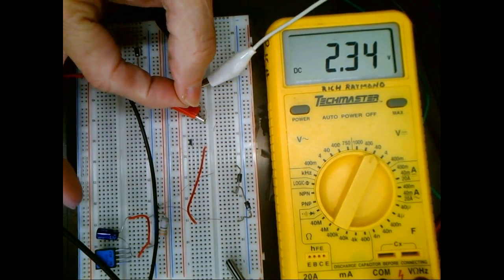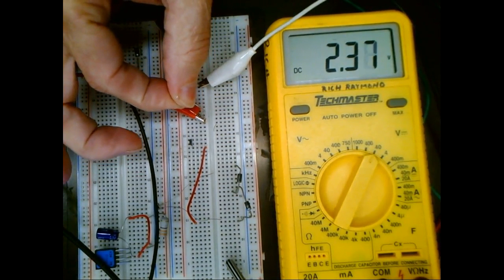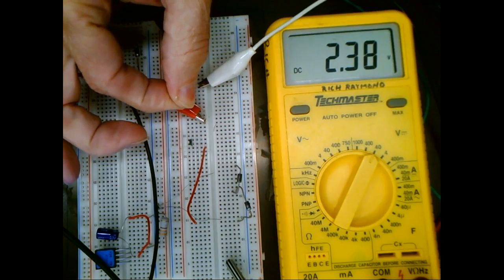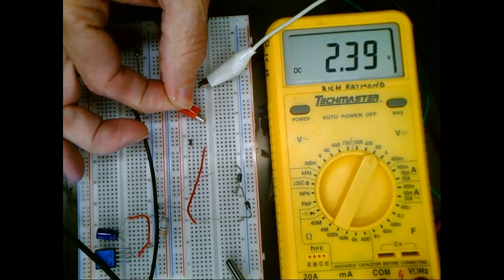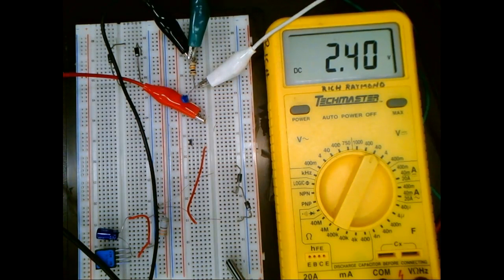And now when I come up and heat this up, my voltage is going what? Up, because I've got my resistor at the bottom. And of course, if I take it off, my voltage should go back down. So now we've taken something whose resistance varies with what? With temperature, and then we're outputting the voltage that's relative to that. That makes sense? Everybody okay?